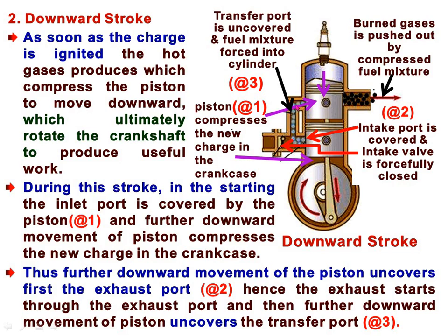uncovering the transfer port. Transfer port means, if the piston reaches here, the top of the piston reaches here, then this transfer port becomes open. So whatever charge has been inside the crankcase with high pressure may be transferred toward the inlet port, and it may travel from there to our cylinder.